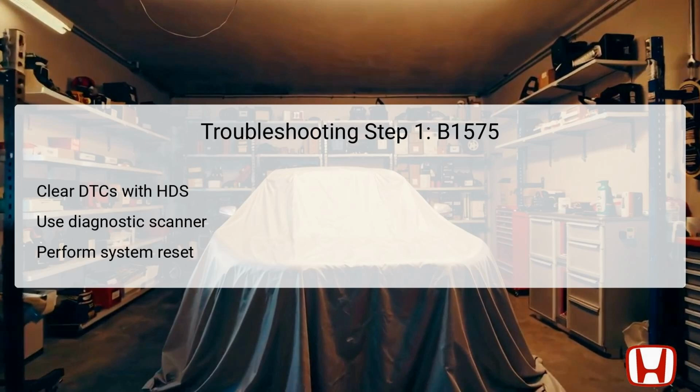After clearing the codes, the technician should turn the ignition switch to the lock position and then back to the on position. Maintaining the correct sequence is crucial to ensure that the vehicle's systems initialize properly. This step ensures a fresh start in monitoring any potential issues, paving the way for further testing and diagnostic efforts.